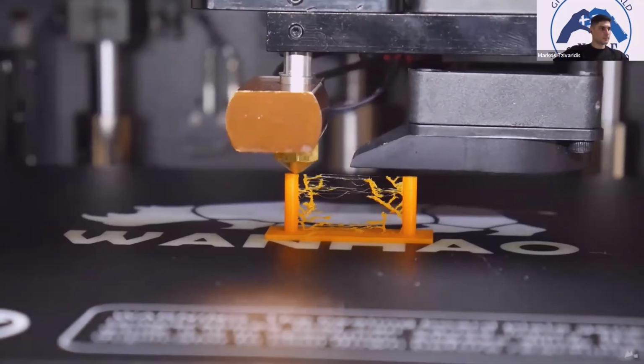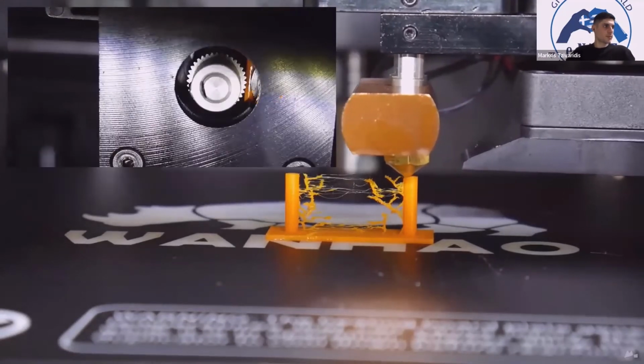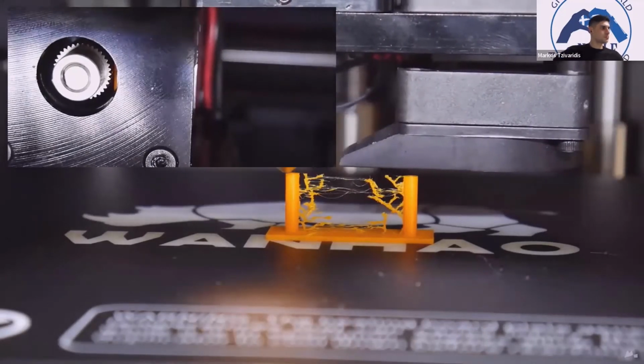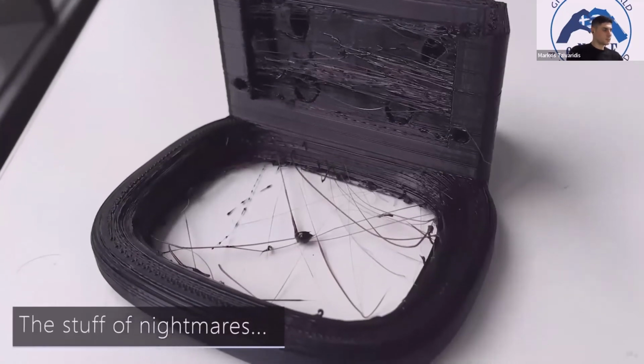Oozing plastic out as it moves between points of the print. You see, as the extruder pushes filament into the hot end, this creates pressure. This pressure wants to equalize. So simply stopping the extruder won't actually stop plastic oozing out of the nozzle. So this can make a print look terrible. And while tweaking temperatures can help to some degree, printing with no retraction will always leave a subpar result when printing complicated models. Okay, great, Angus, but how do we stop stringing?